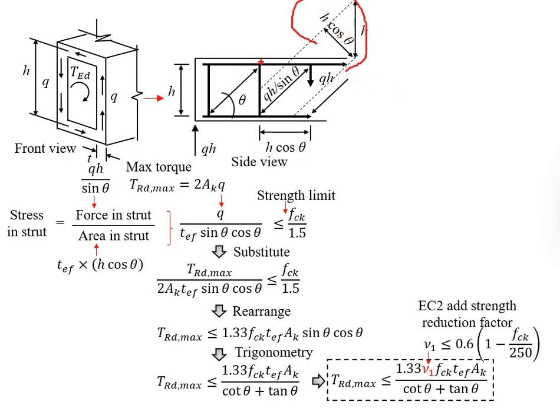Having this being brought into the right angle triangle here, you have an angle theta here. Now you know this horizontal component here equals h cos theta. Now you see this vertical force here, based on the free body diagram, it will be resisted by this force, so that the sigma Fy will be equal to 0.